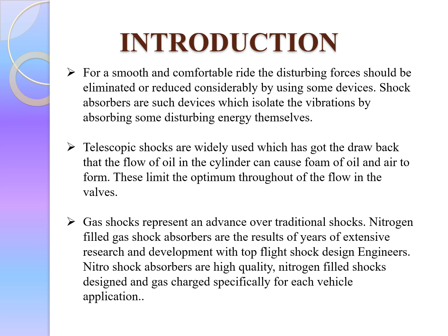Telescopic shocks are widely used, which has the drawback that the flow of oil in the cylinder can cause a foam of oil and air to form. These limit the optimum throughput of the flow in the valves. Gas shocks represent an advance over traditional shocks. Nitrogen-filled gas shock absorbers are the result of years of extensive research and development with top flight shock design engineers. Nitro shock absorbers are high quality nitrogen-filled shocks designed and gas charged specifically for each vehicle application.